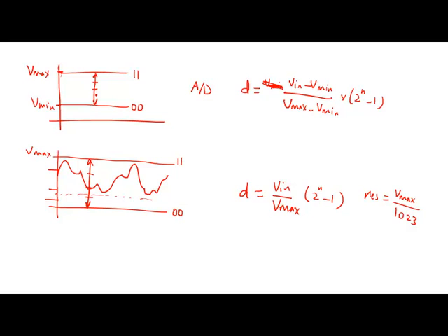Divide this range into 1024 or whatever number of segments you want. So here your resolution is going to be Vmax minus Vmin divided by 1023 or 1024. This is going to be important. You're going to have homework problems that talk about this and make this distinction. So you get a higher resolution, better than that 3.22 millivolts, if you condition your A to D to map 0 to here.